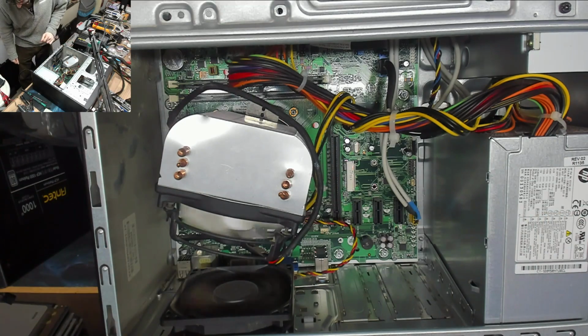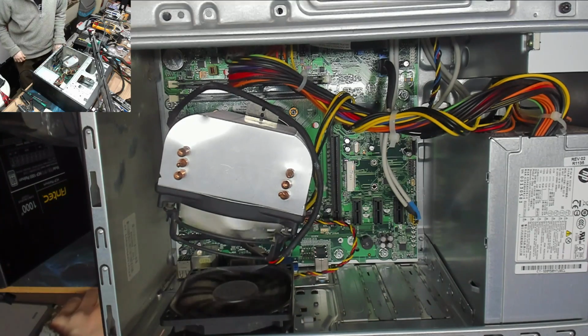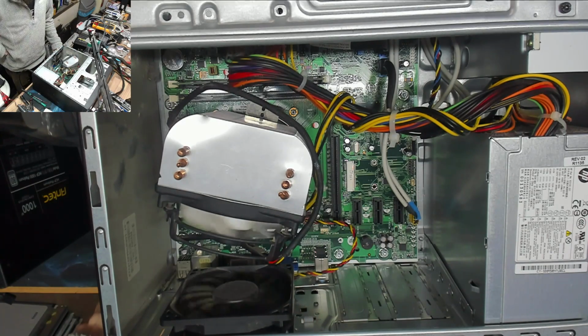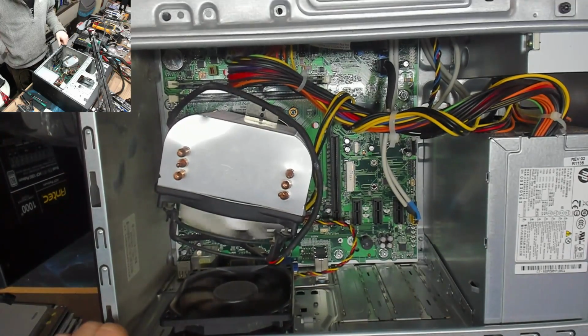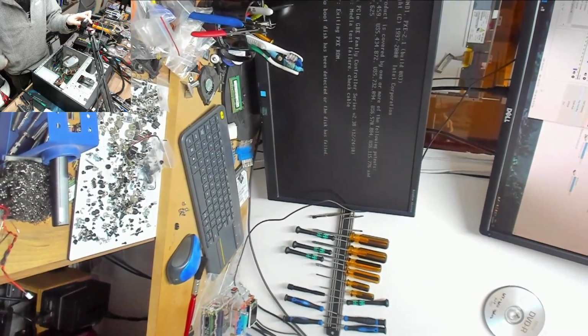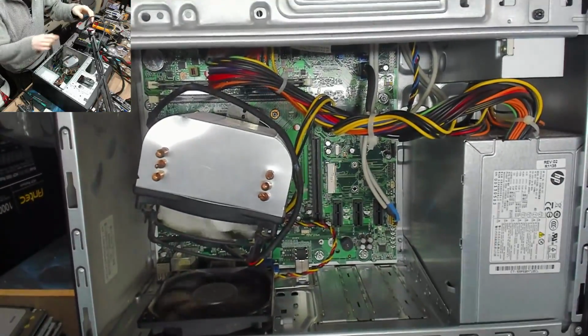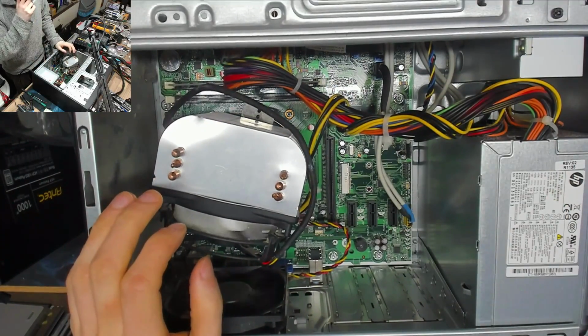And I haven't plugged in a VGA lead. Plugged in a VGA lead and the monitor has gone green light. And we have a post with the correct CPU as well. And it's gone straight to no boot disk detected, which again I'll just show you there just for posterity. No boot disk. Okay. Right, well, it looks like this motherboard is shot.